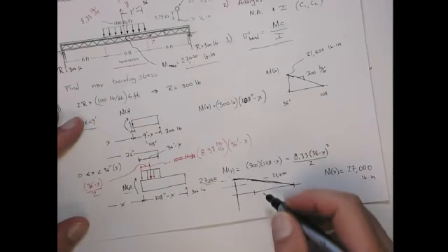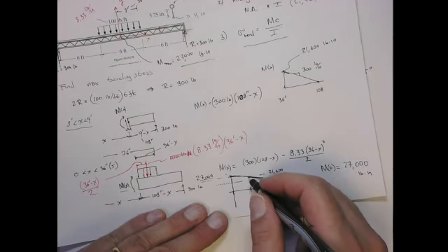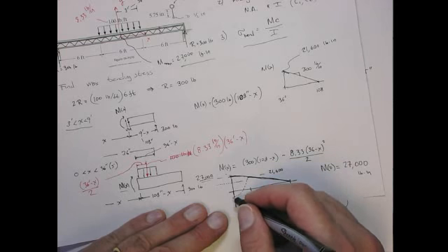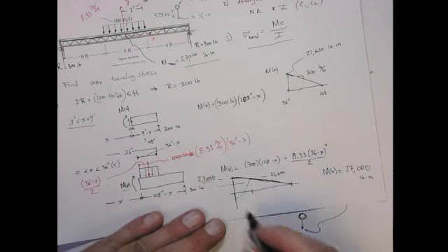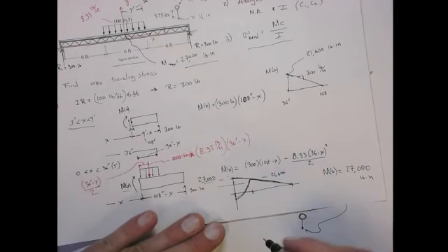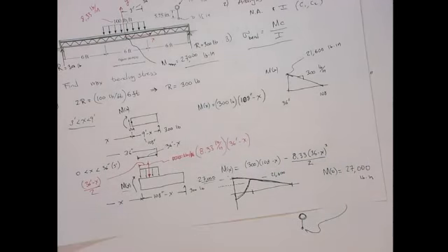And this bending moment diagram looks odd. I would actually expect that this bending moment diagram would then drop down like this, okay, and give me a negative stress there. But I have a suspicion that it should actually do this. Let me check that. I'll stop the video now and see where my error is.